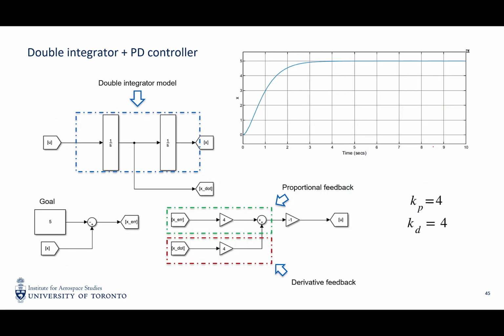In addition, if you are going to apply this on a slightly more complicated system and you do not want to calculate zeta and omega, I will also provide you a way to manually adjust by trial and error, so that you can tune the PID to achieve better performance.